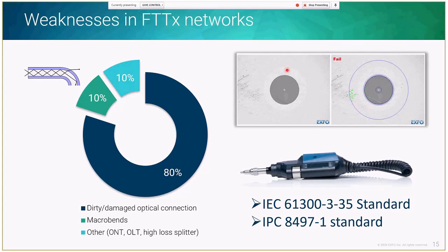For example, manufacturing, when they supply the equipment, they would need to have a fully clean fiber. So in the field, you may allow some smudges or particles, or just very tiny particles that you can accept in the core, and your equipment will not fail. So if I have this fiber here, because it's scratched, then the software will show it's a clear fail. And in terms of ITU-T, the recommendation given in G.650.3 is inspect, clean if needed, and then inspect again.